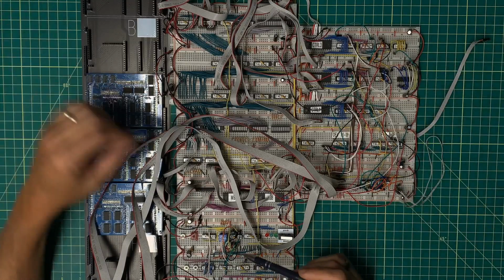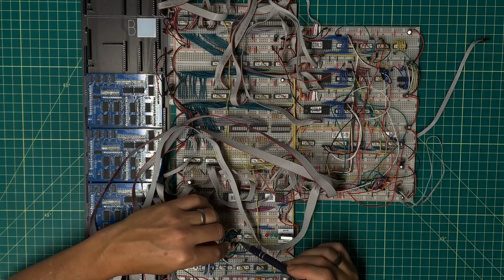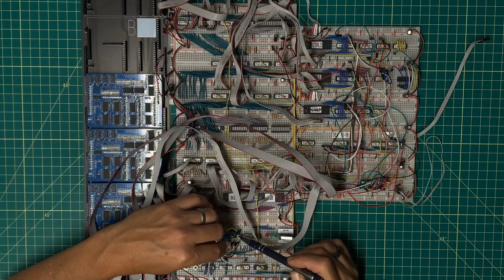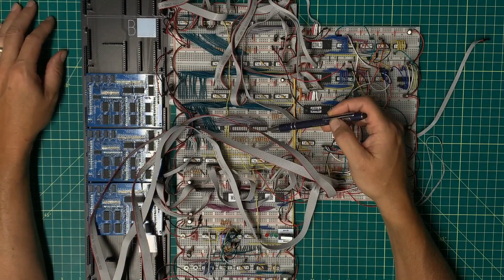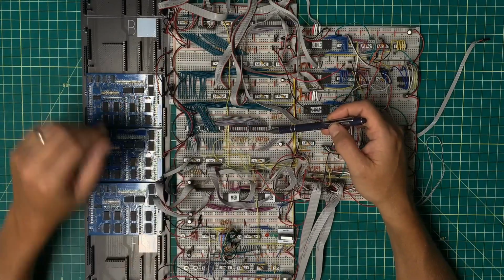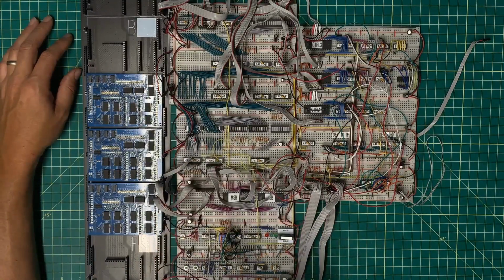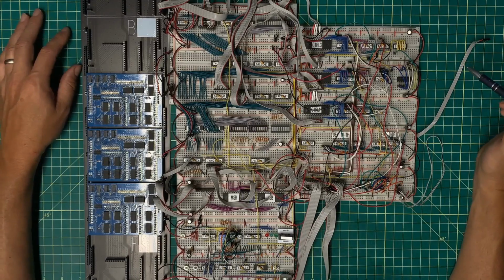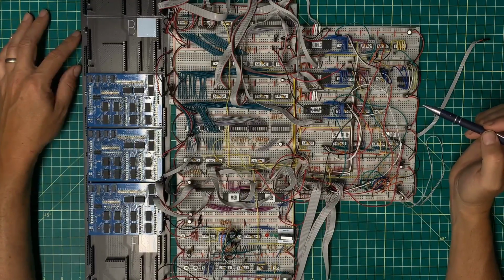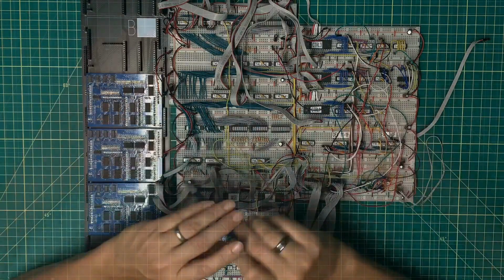The second section is now down here, which was added after all of this mess. And this is related to the reset circuitry to make sure that the AND latch of the first instruction after resetting happens after the program counter asserts onto address bus 1 what its intended value is, giving these two ROMs a chance to settle that address out and return the actual data. So the first place to start is up here in the corner. And I'm going to start by looking at data sheets.